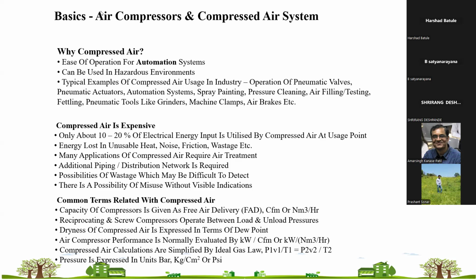Then there will be load pressure and unload pressure. Such terms are used in compressors. Then there will be specific energy consumption. It is a measure of the efficiency of a compressor, or we can say the performance measurement criteria of a compressor, where the majority of compressors are sold on this particular criteria.